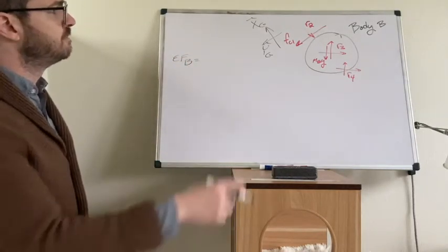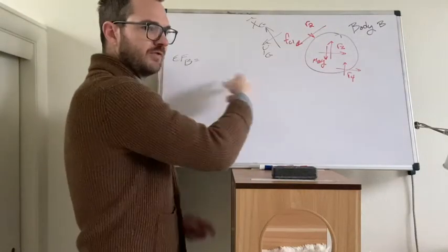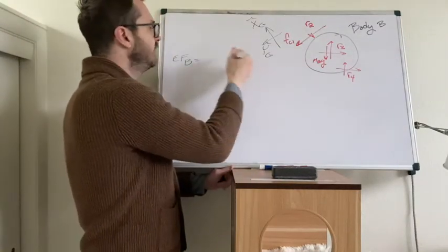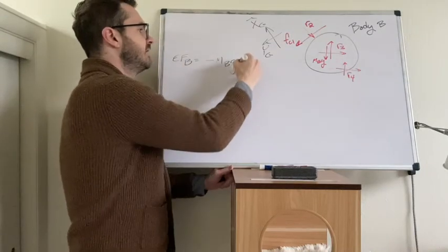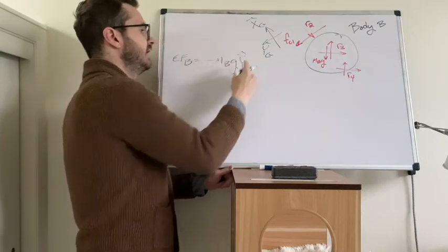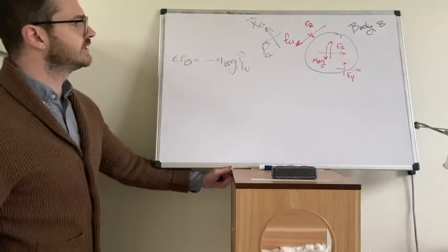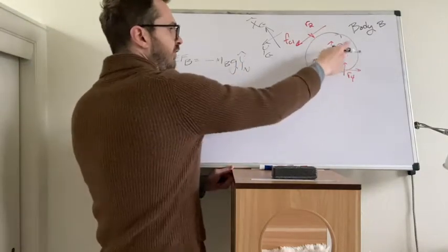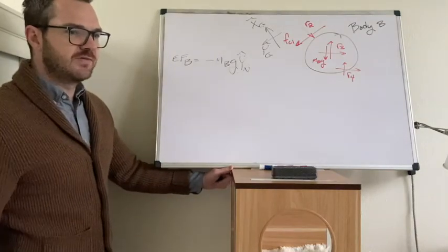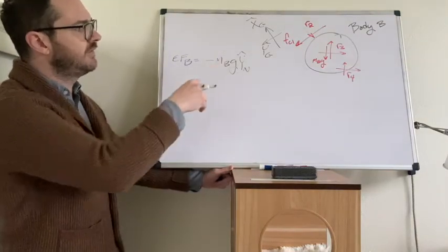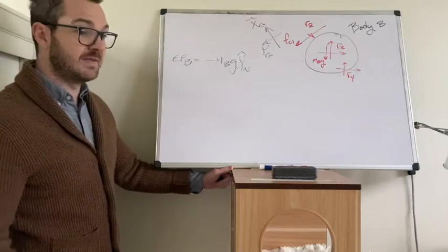Next, we just take the forces, write them in. As usual, let's start with gravity, knock that one out. MBG in the negative y hat n direction. Next, R3 and R4. Let's just stick with the previous convention. For this problem, let's put all of these reaction forces in the n frame.